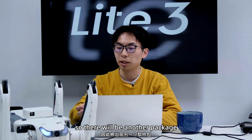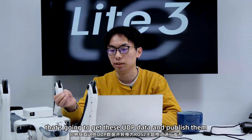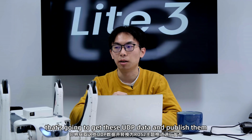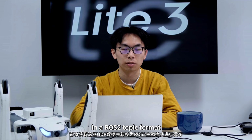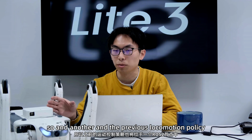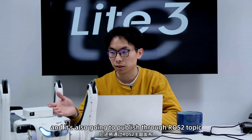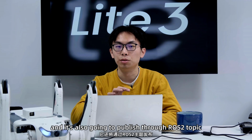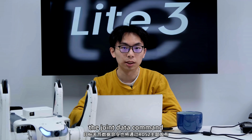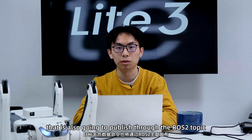There will be another package that gets these UDP data and publishes them in ROS2 topic format. And the previous locomotion policy will also be a ROS2 node, and it's also going to publish the joint data command, the target joints, through a ROS2 topic.